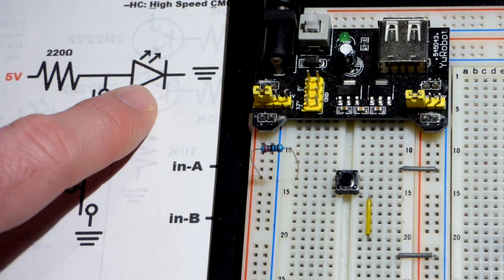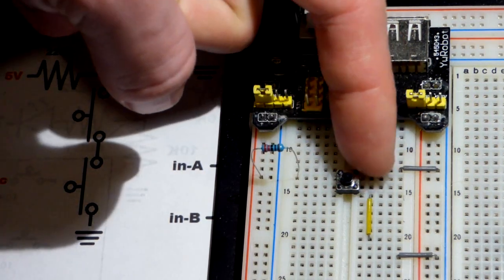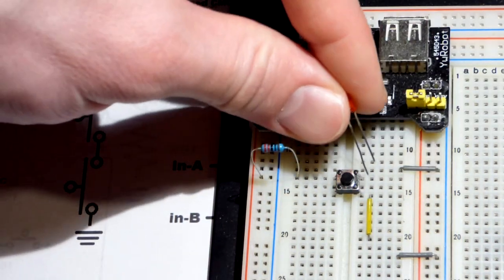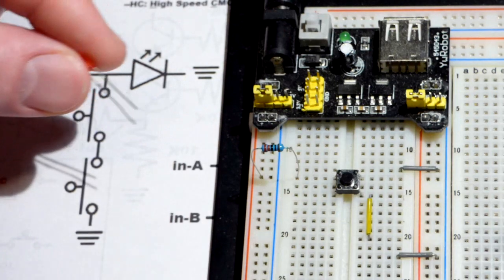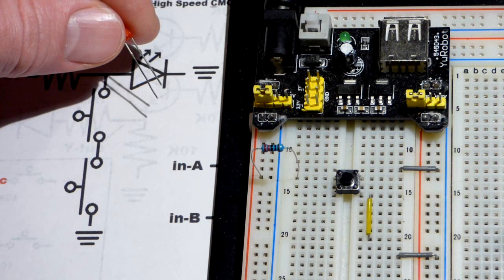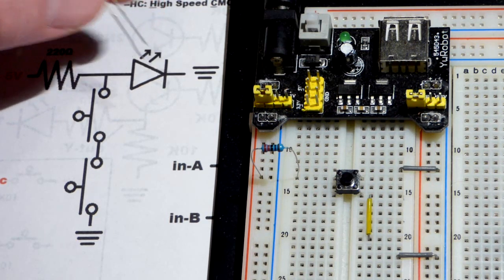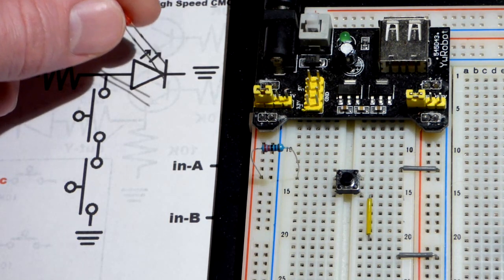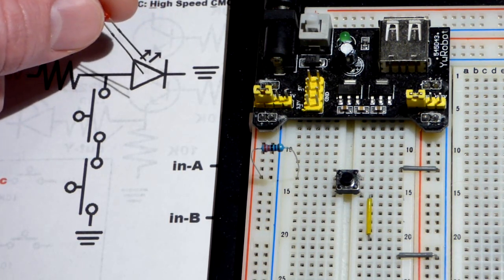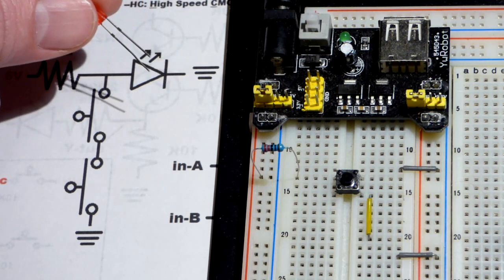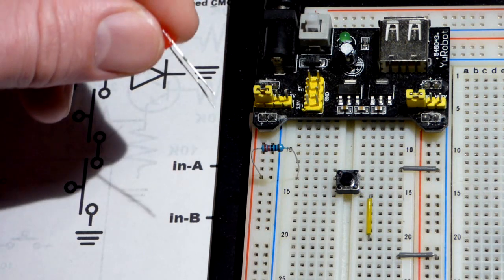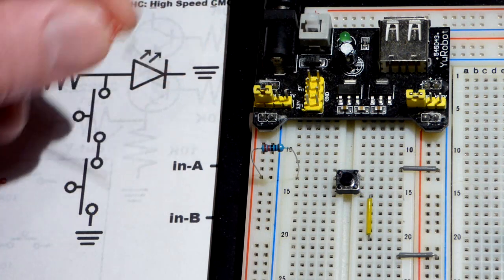Now we're going to grab this LED. So I have a jumper up here. It's 1 space away from where the top pin for the switch is up there. The long lead, the anode, is this side of the schematic symbol. The short lead, the cathode, is this side where this dash is. With a lot of diodes, there's a black or different colored stripe where the cathode is. But with the LEDs, we're dealing with a long lead for the anode, short lead for the cathode, as long as we didn't trim them. And the cathode also has a flat edge right there.